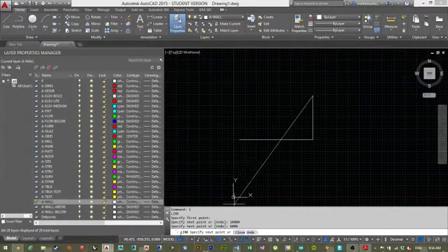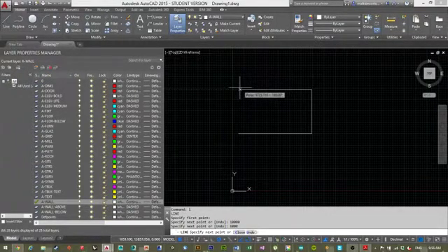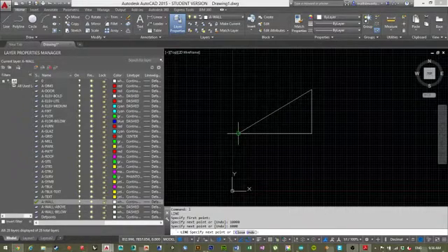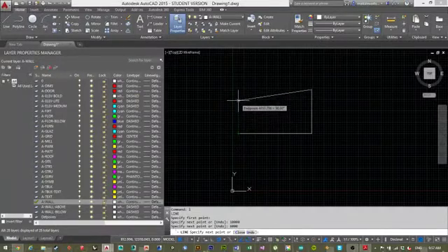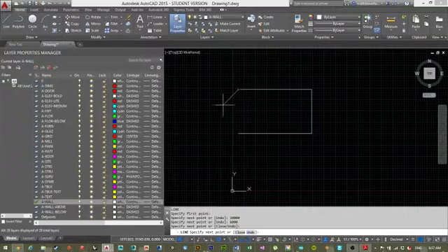And as long as you haven't turned all these things off, you should see that. AutoCAD has something called, I think, tracking. If I wanted to end something right in line with this, since I knew I just typed in 10 meters, I could just type in 10 meters like this. But if you go down here and hover over it until the green box comes up, and then drag it up, you'll see that it now has those construction lines, both up and on the 90 degree. So it's easy. Click there, it's going to snap to that.